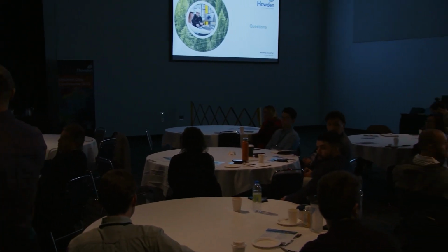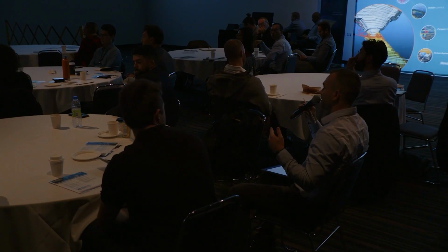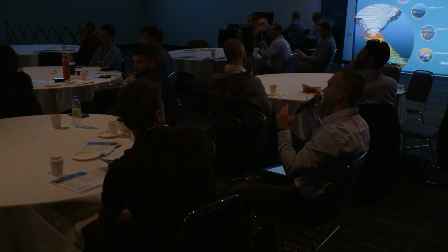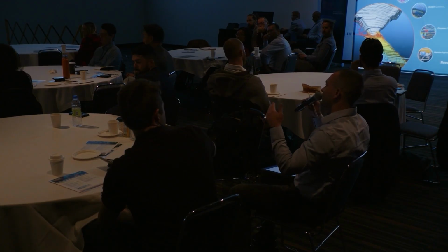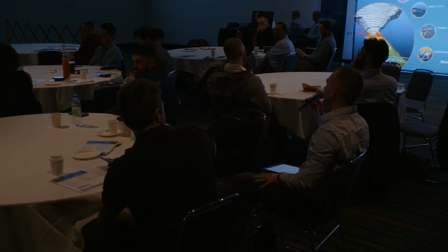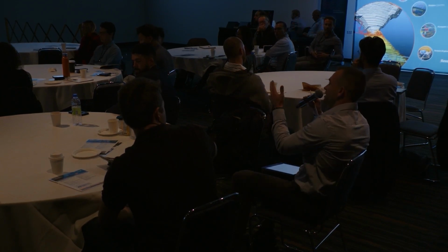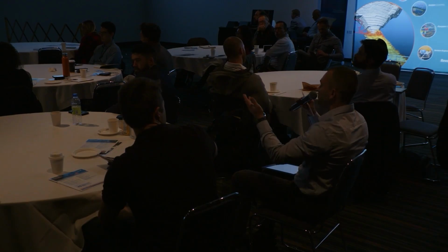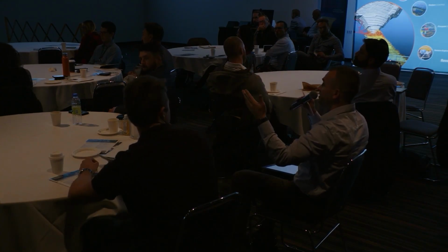Thanks for the presentation. That was really good. The wet bulb and WBGT, it comes up all the time in North America. ACGIH, that's the heat stress index, wet bulb globe temperature. This is more of a comment. When selecting these systems, I have personally found it difficult to interact with clients talking about WBGT, that's a heat stress index. And then the wet bulb, it's not a heat stress index in North America, but it is in South Africa. But that gives you the energy of the air. Essentially, a dry bulb is a very, very small component of the energy of that air.